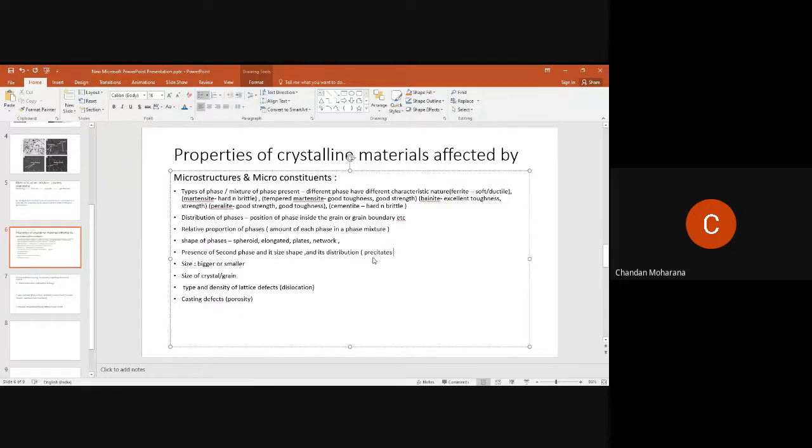If you remember, precipitate forms when there is limited solid solubility. Suppose you have a steel and you have added some chromium, for example, a large amount of chromium. The steel may be ferritic, it may be martensitic, depending upon the microstructure. Suppose it is a ferritic steel. The matrix is ferrite, but the chromium is not so soluble now, and you have carbon in it. So what will happen? Chromium carbide will form. The chromium starts reacting with the carbon because chromium solubility is decreasing, forming chromium carbide, and chromium carbide is a precipitate.